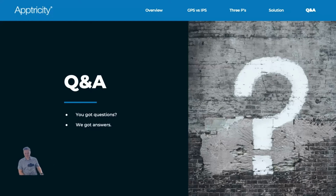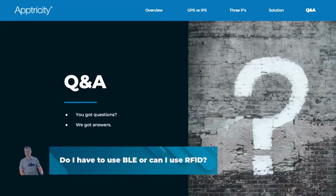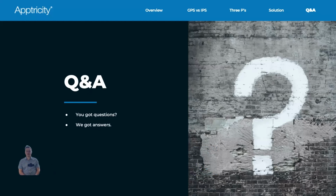All right, first question. Do I have to use Bluetooth, or can I use RFID? This is a question that we get pretty frequently, because RFID is cheaper than Bluetooth, but you cannot really use passive RFID in the solution, because it is exactly that. It's a passive tag. One of the key components of an IPS system is the fact that the beacon is broadcasting, and it's making its way to the Bluetooth antennas, the Bluetooth readers, as opposed to the readers having to go all the way to scan a passive tag. So the fact that Bluetooth is an active beacon tag is what makes IPS work.